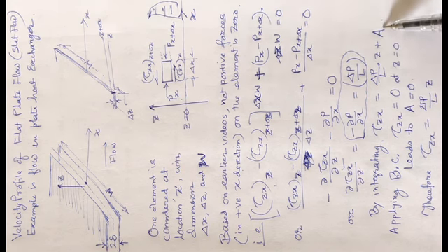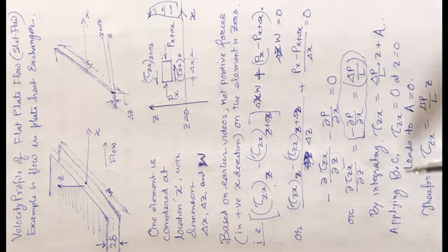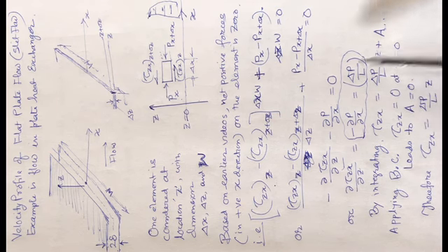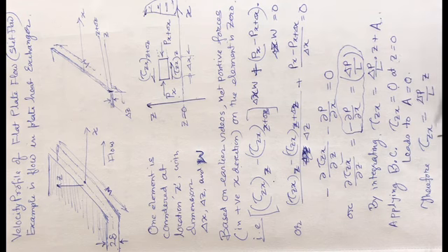Again, you see, this is the constant of integration. So now the boundary condition is applied. Tau zx is equal to 0 at z is equal to 0 leads to a is equal to 0. It means tau zx is equal to delta p by L multiplied by z.